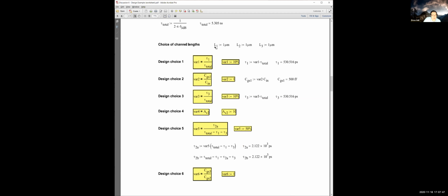All right, then I pick my channel lengths. In this particular design, I'm leaving these as kind of independent variables to start with. And then I go through my design choices that I calculated before, and I use my starting values. So 10% 1, 10% 10, and then 50% here. Lastly, 1 for the ratio of CGS2 to CGS3.